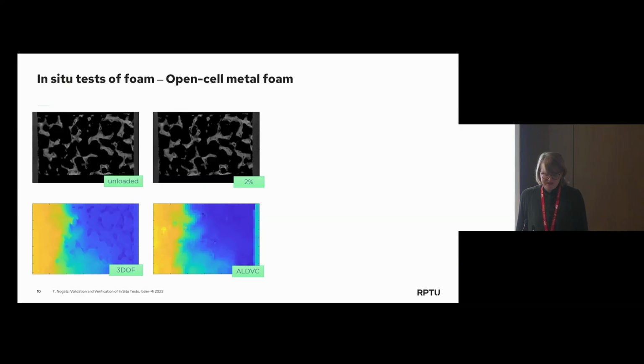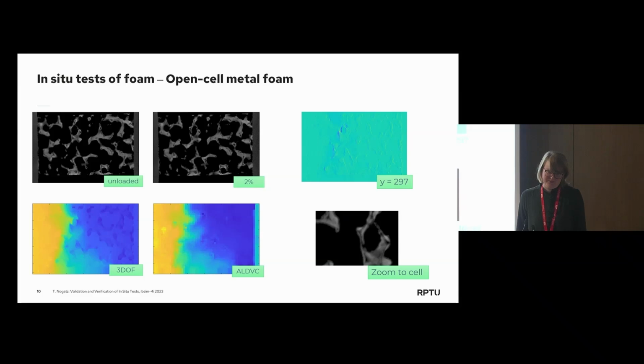So in elastic stages, it's very important to properly map the displacement such that you can predict where the foam will fail. And if you now compare the voxel-based method by optical flow and the RDVC, you actually see exactly that happening. DVC will overlook the local failure, where the voxel-based method managed to find it. And we can calculate strain on that. Within the strain, we really see the local extrema that mimic the failing cell. And what is also very nice if you have voxel-based full-field displacement is that you can use it to really follow your foam, or your cell, while it fractures.